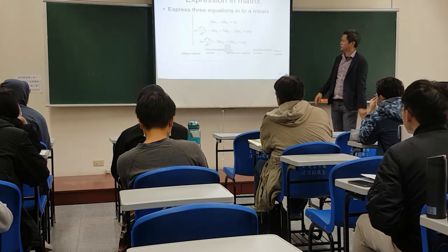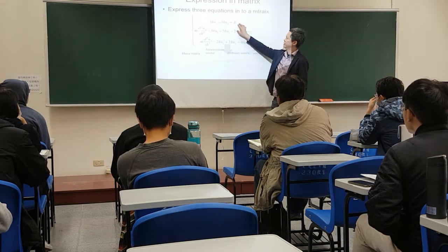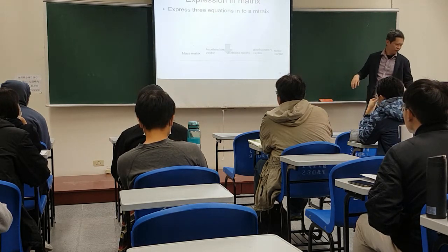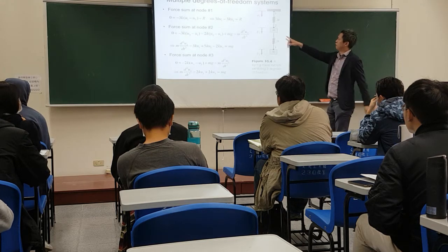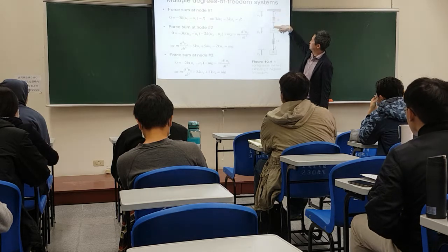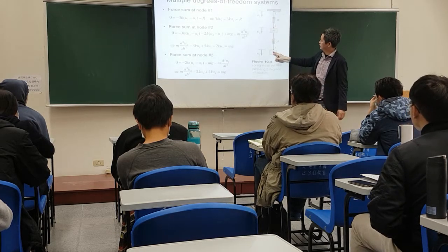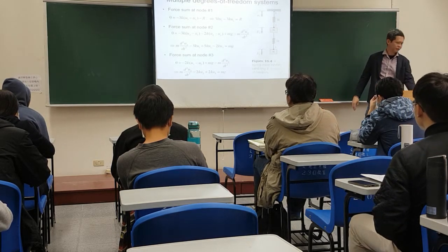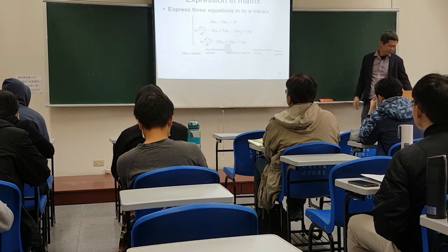form. So these are the 3 force balances. So how do you write the force balance? For each node, you have 1 force balance. First at the anchor, second at the mass, and then third on the lower mass. So you now have the 3 equations.